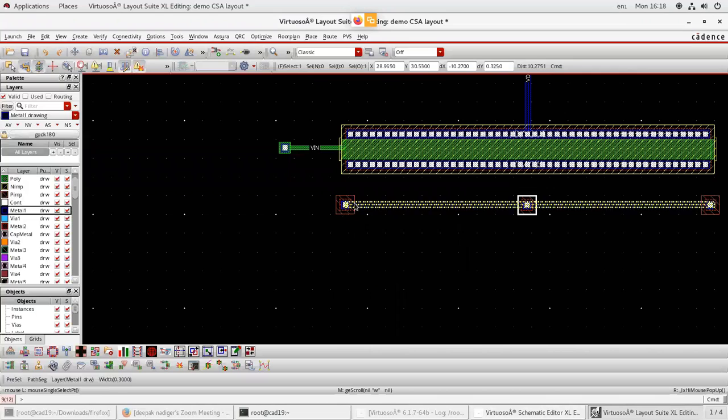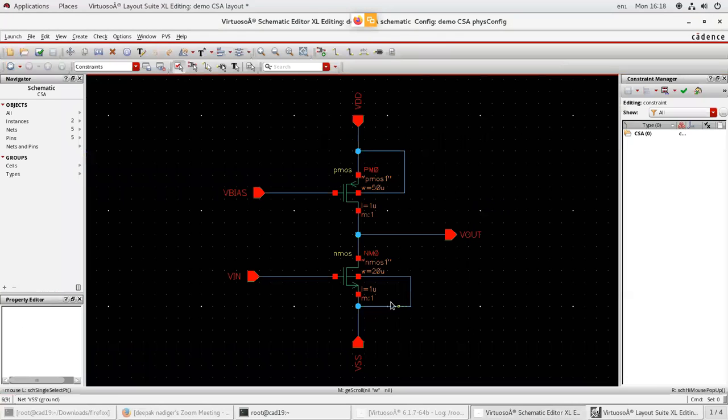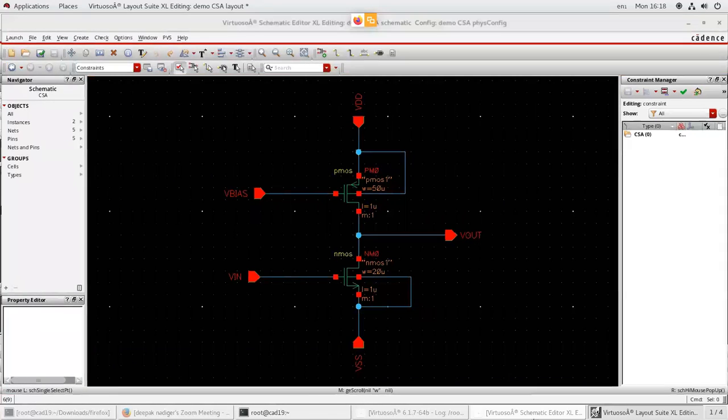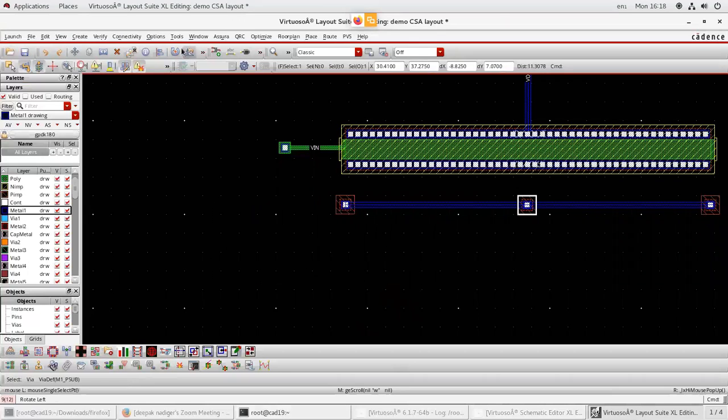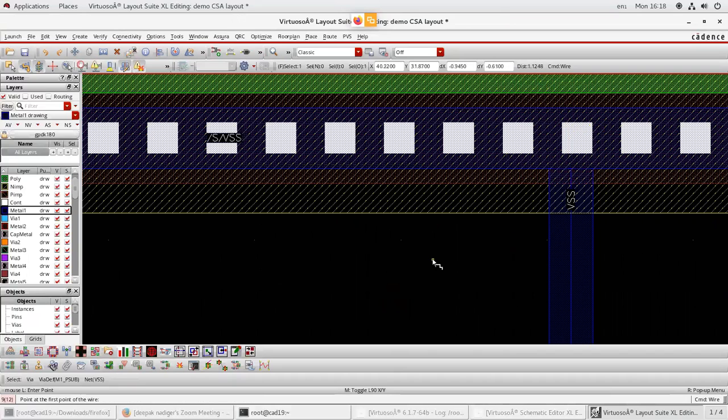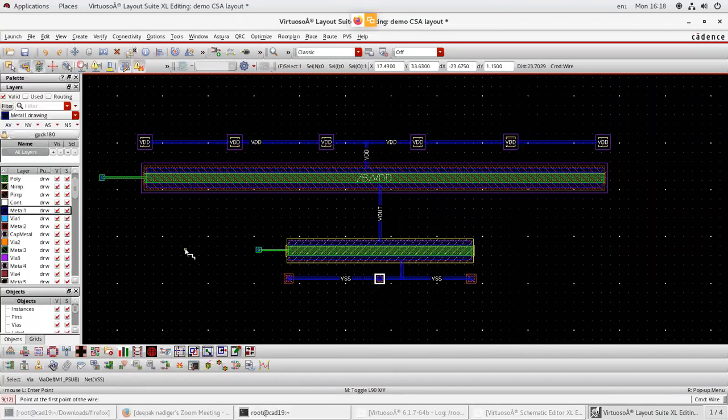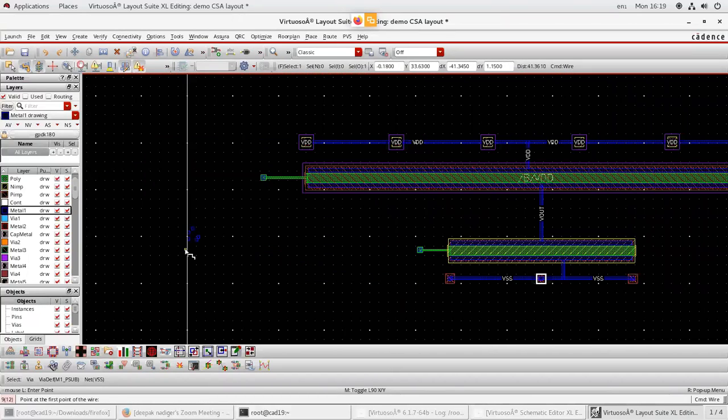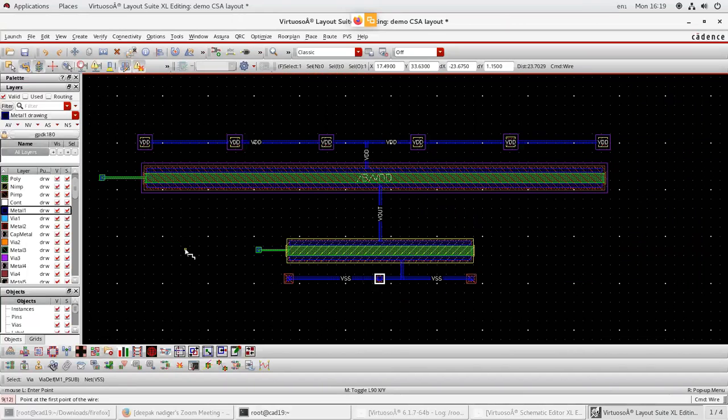And these wires which you have shorted are going to act like a substrate. So this substrate is connected to the source of NMOS. So I can connect this to the source of NMOS. Okay. So after this, the only last thing left is placing the pins.